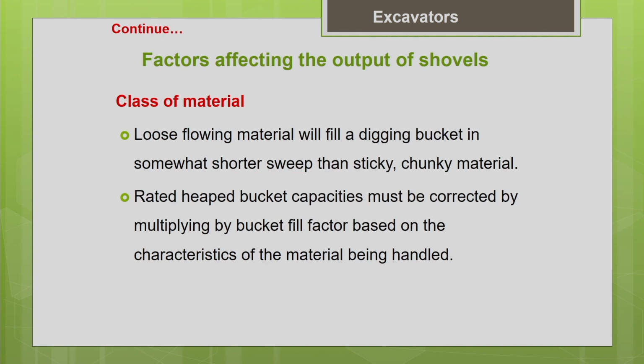The first thing which we are going to discuss is about the class of material. So how the material type will affect the productivity of the machine. Obviously, when you are going to handle some easy flowing material, like loose flowing material like sand, you can easily fill the bucket in a very shorter sweep. But if it is going to be a sticky material or rock or chunky material, in that case it may take more time to load the bucket.